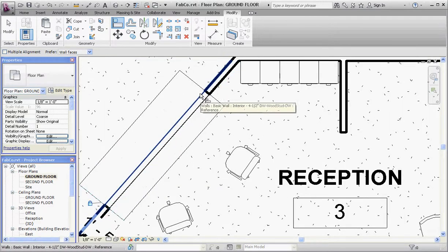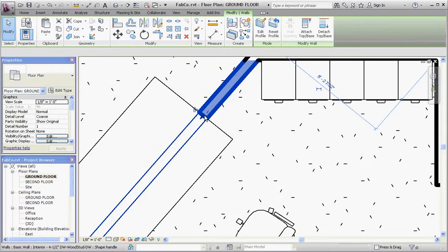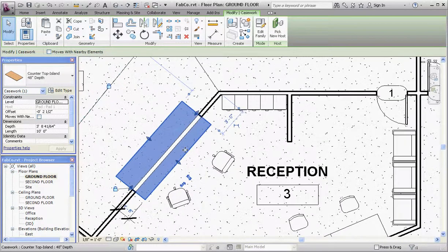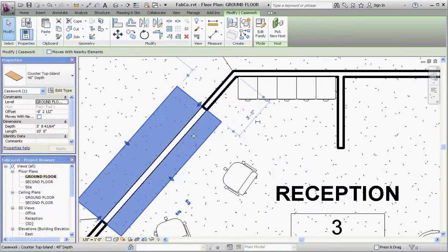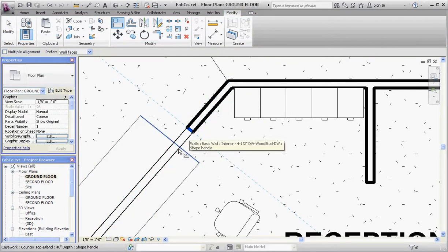And if we click on the countertop itself, if you don't get it otherwise, it should show you what those locks are if we have those in place. It doesn't really have it, so let's go ahead and stretch that back out. Go back to the alignment tool again. That is our static element. This is the movable element, and let's go ahead and lock that into place. So again, if we select the countertop now, we see all the constraints in there.